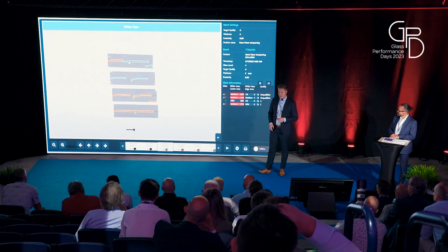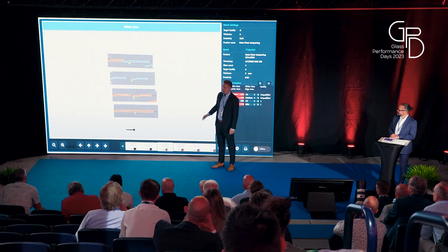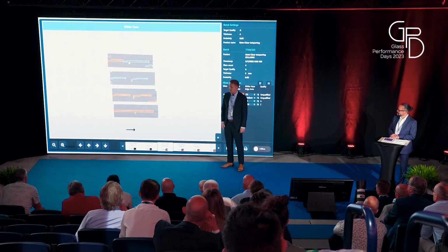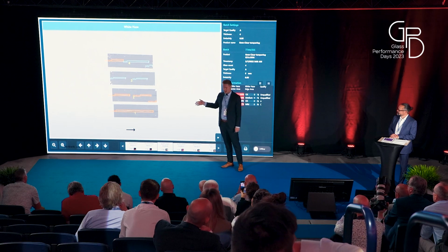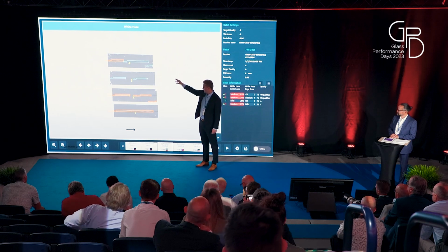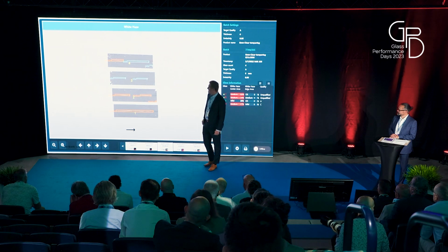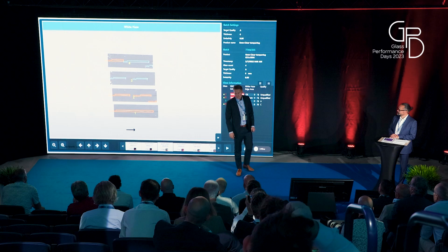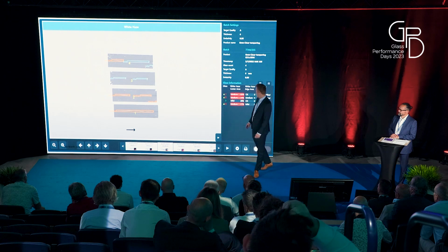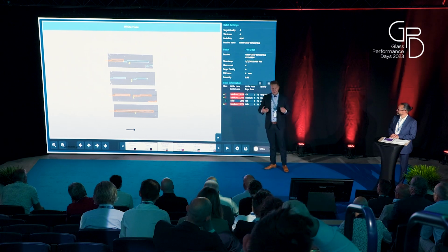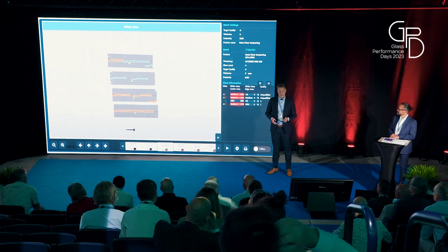And what the scanner then gives out is an image of the loading that was just scanned. So 4 glasses coming out of the tempering line, and the system is automatically highlighting where white hazes have been detected, if they are there. In this example, the system has detected a couple of medium hazes, which would be these orange ones, and then 3 or actually 4 blue hazes, which are mild categories. And this information is then automatically available to the tempering line operators. And of course, you can set certain parameters so that you get automatic alerts if, for example, strong hazes are found and you want to react to this immediately.